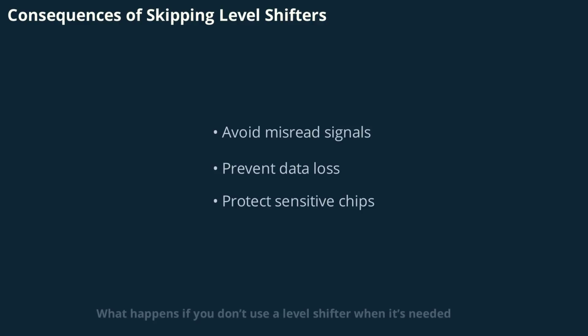What happens if you don't use a level shifter when it's needed? The results can be disastrous. Signals may be misread, leading to unreliable communication or data loss. Even worse, sending a 5V signal into a 1.8V input can permanently damage the receiving chip. That's why level shifters are not just a convenience, they're a necessity for protecting your hardware and ensuring reliable operation.